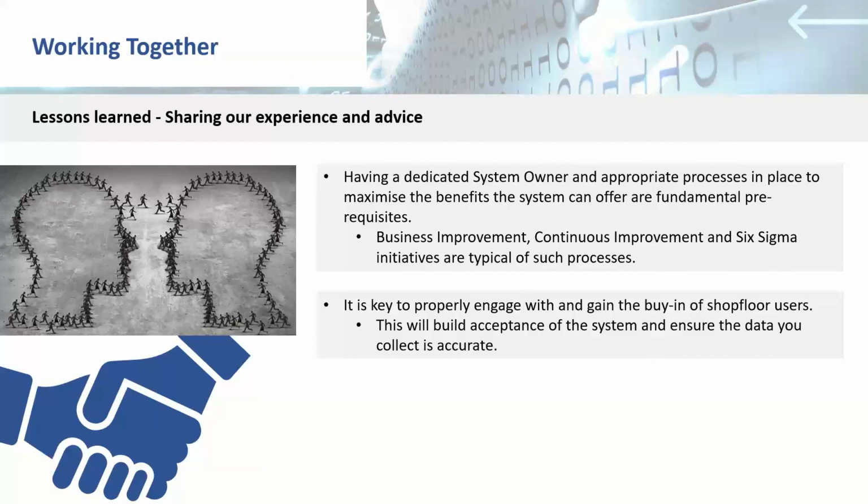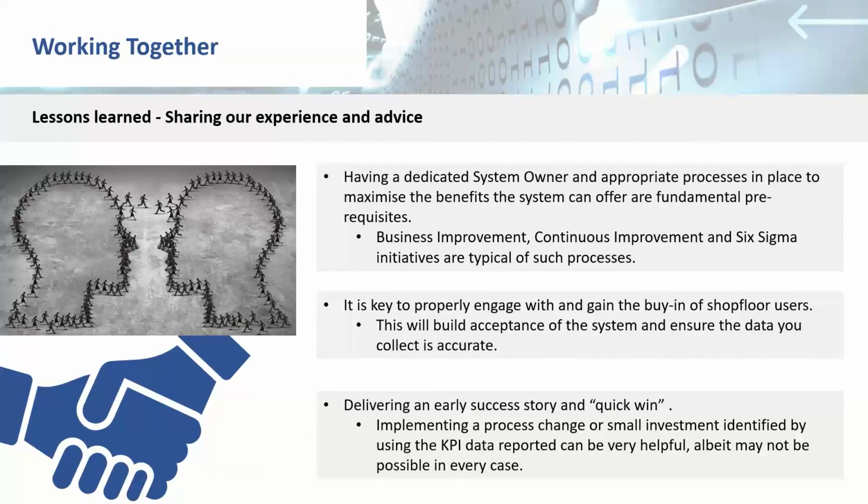Secondly, engage with the shop floor users early on. They're going to be booking and recording a lot of the data. Get them to understand why you're doing it, what you're doing. Ask them the sort of data that they should be recording. If there's downtime codes that you're going to be looking at, then they will know what those downtime codes are. So they're the best people to ask.